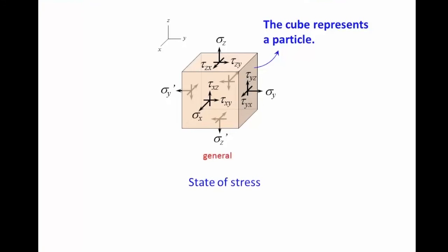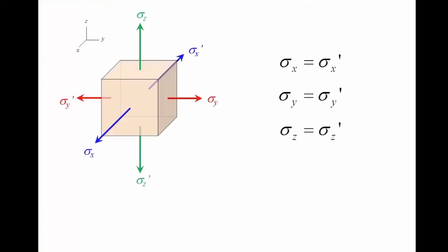If you recall what I mentioned in the introductory video for this course, in mechanics of materials, we still only study objects that are in equilibrium. Therefore, the equilibrium conditions still apply. Derived from the equilibrium conditions, we can have the following two conclusions. First, the normal stresses along the same direction must be pairs with equal magnitudes and opposite directions.